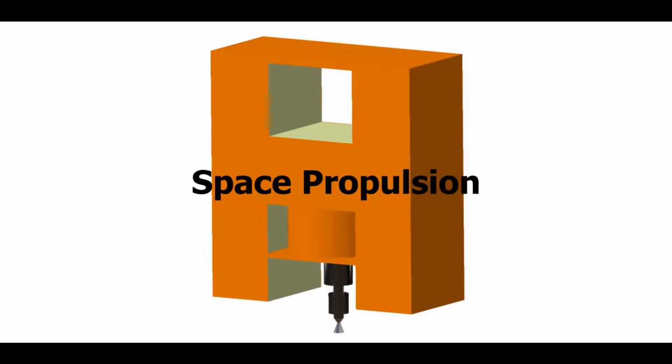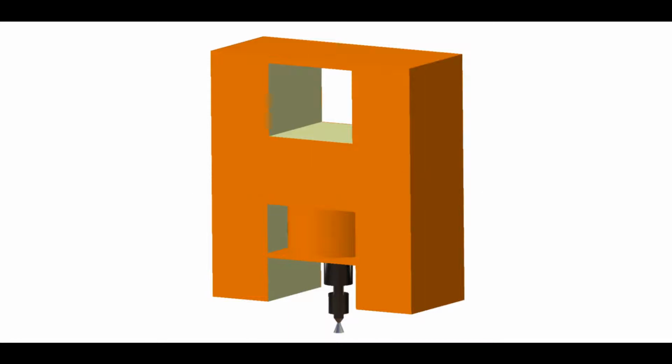Hello, my name is Gustavo Ribeiro, and I'm the responsible of the space propulsion area of the Moon Invaders team. First, we started by doing a thorough research about the CubeSat missions already done and which type of propulsion system they used. One of the main problems we identified was that there aren't almost any chemical propulsion systems launched or being planned for use in CubeSat missions. This is due to the piggyback launch nature of CubeSats that forbids them to put in risk the main payload of the launcher, and this would automatically exclude the chemical thruster option.